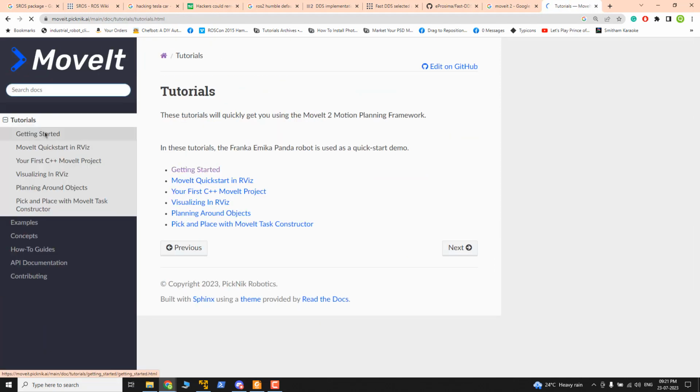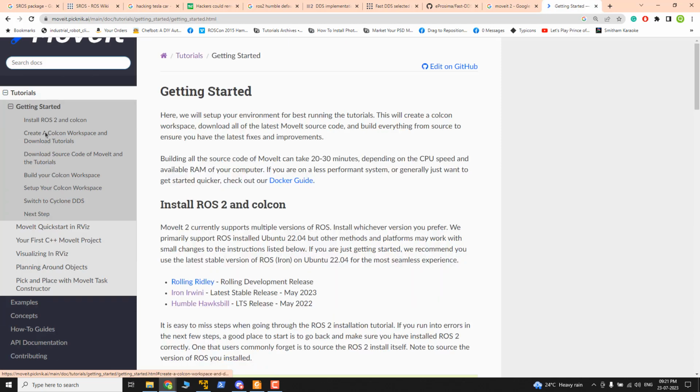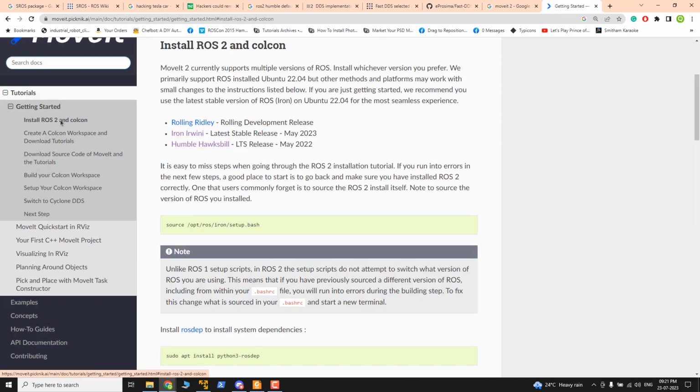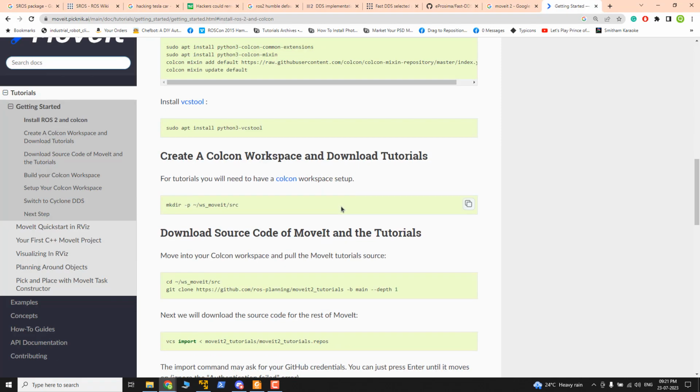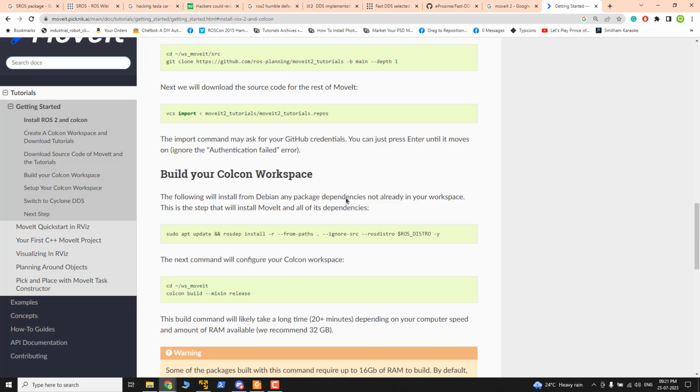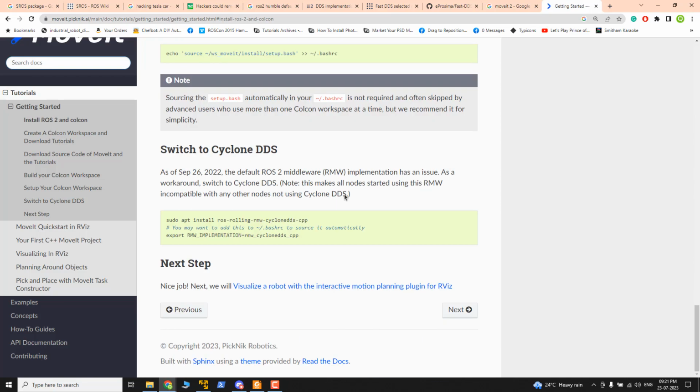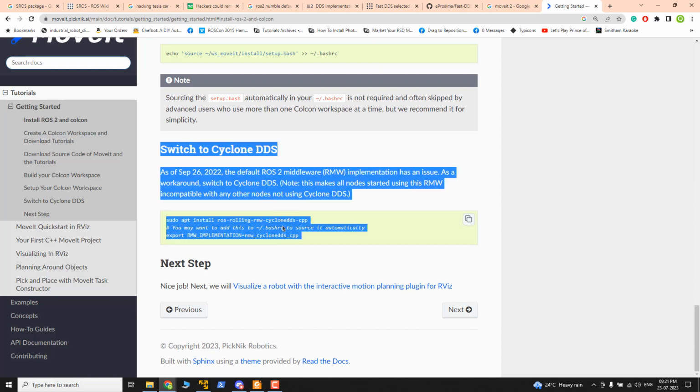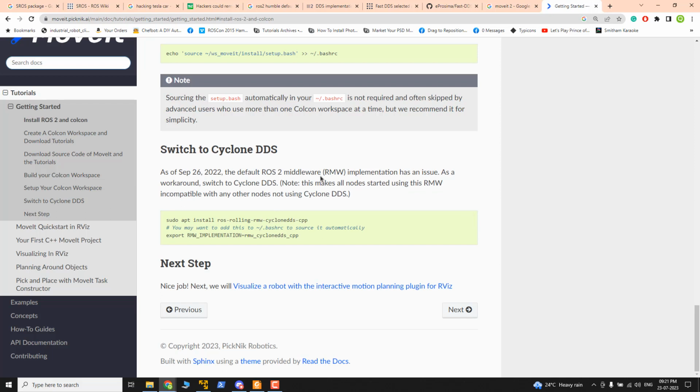Okay, I will show you that. Yeah, here. So if you're working with Fast RTPS or Fast DDS and planning to work with MoveIt, Cyclone DDS will be a better choice.